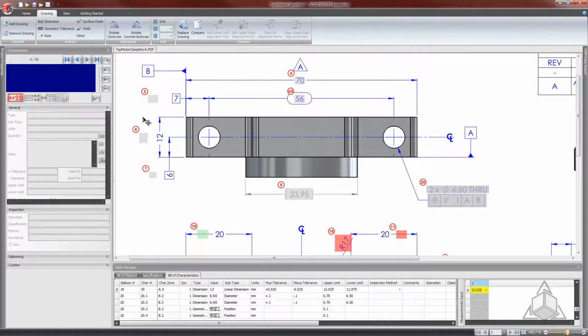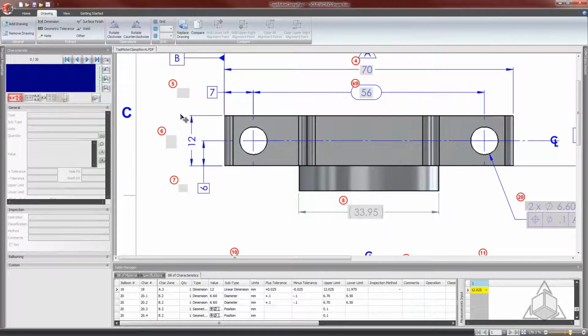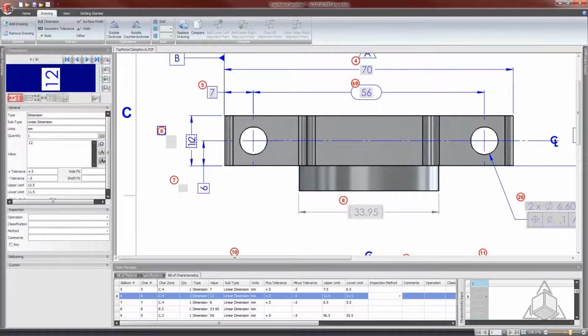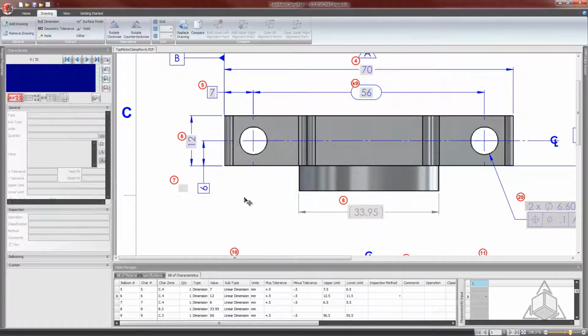Now, taking a look in the upper left-hand corner here, this is where our image capture windows are. So what I can do is I can just kind of move this capture over. I can resize it a little bit, right? And once I make my change, this used to be a value of 12. I just recapture this and it's 7. So if I had specific properties already associated with this, it's really quick to just adjust both of these, click on your rotate and recapture, and it re-updates everything that you've got going on. So SolidWorks Inspection has the ability to do all this stuff for you. So this is better, totally better handling your PDFs, especially when you're getting in revisions.